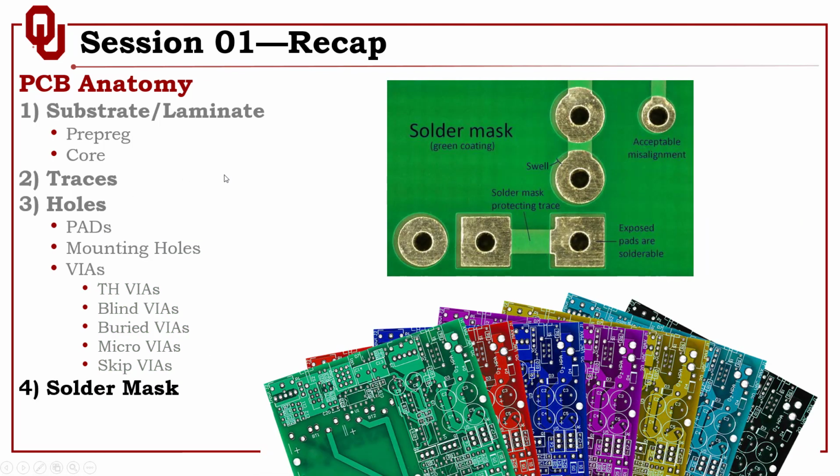So the fourth element we talk about is the solder mask, which is a thin polymer layer deposited on the top and the bottom layer of the PCB. This protects the outer layer, or the copper on the top, from oxidation and prevents solder bridges when you do soldering, because you see the solder mask in here separates this pad and this pad. So if you are soldering this pad, this will help you not to over-solder onto this pad as well.